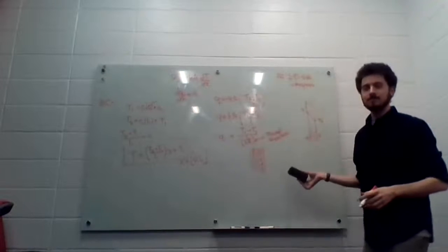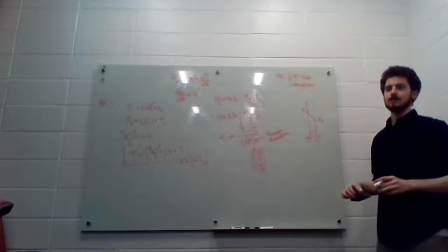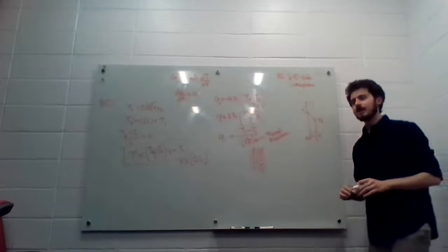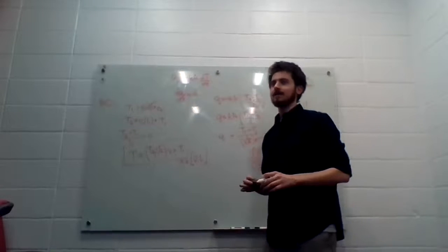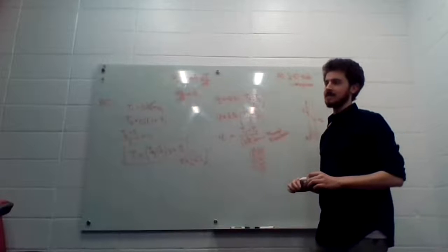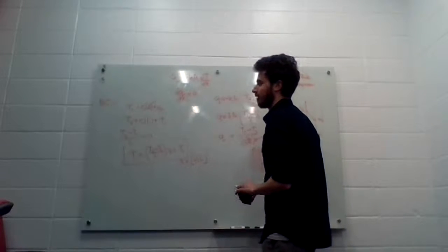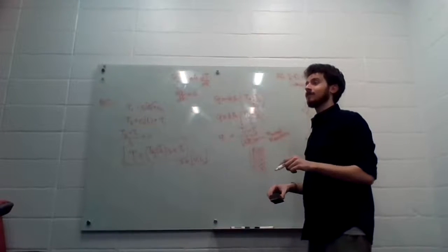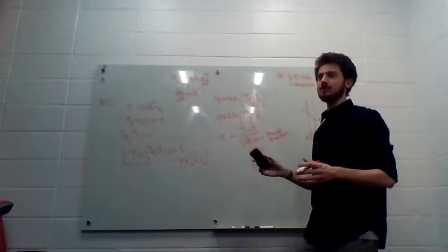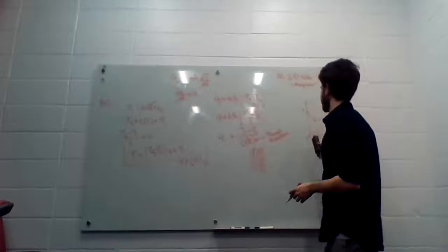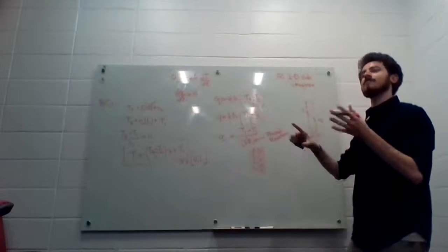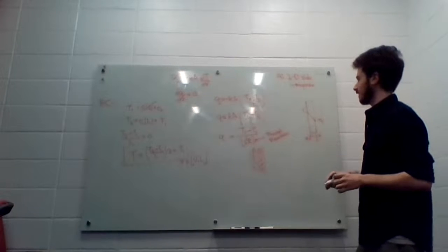Yeah. It's exactly the same as electrical engineering. You've got thermal resistances, you can stack them up in series, and they act like a series circuit. You can stack them in parallel, and they act like a parallel circuit. It's a perfect analogy, predicated on these nutty assumptions we have about infinite materials and one-dimensional stuff, which isn't really true. You start to see that when you get to really complex things where you really do have three-dimensional effects. We'll do that later.